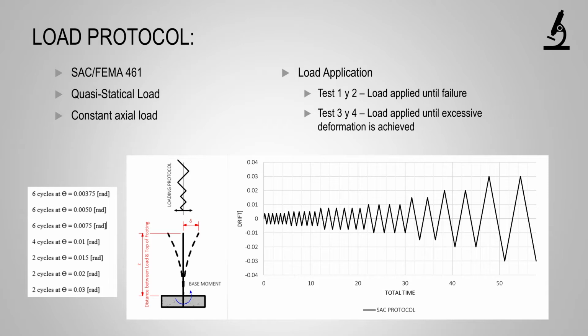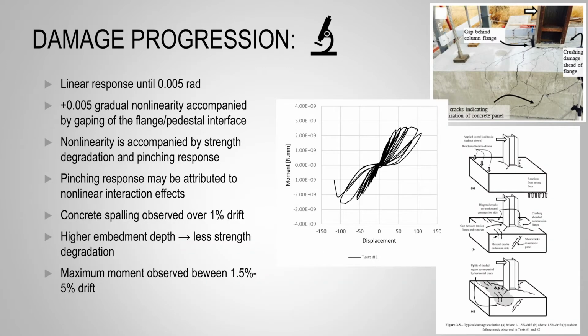Also, it's important to take into account that the loading protocol plays an important role in the connection response. This is due to the fact that the non-linearity in the connections occurs mainly due to the effects of interactions between the two components. From the experimental analysis, we can see the following damage progression.